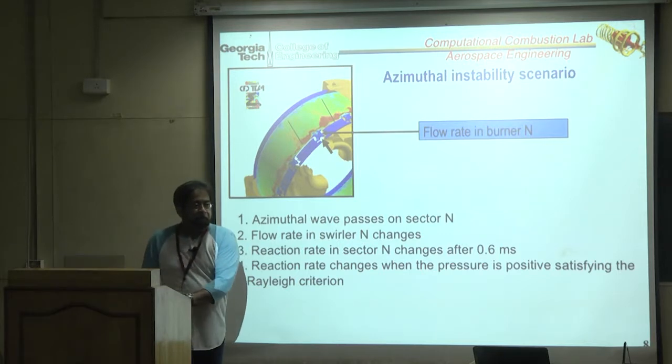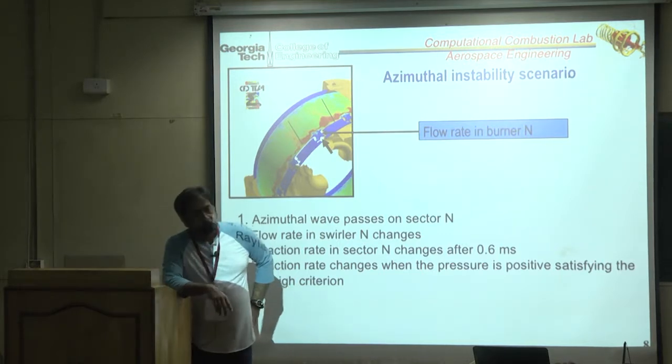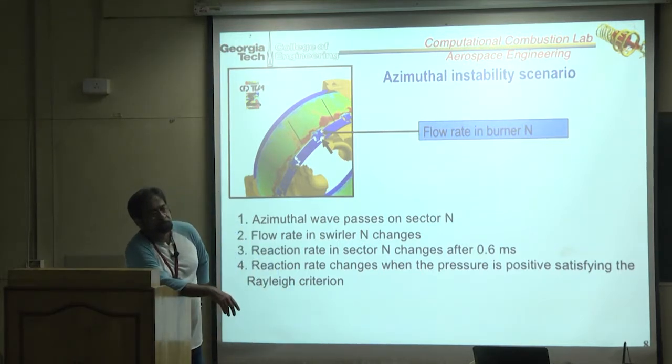Last session you mentioned that if you are going from fine grid to coarse grid, it's okay because we just eliminate some turbulent eddies. But if we have fine grid, then coarse grid, and after that fine grid again, there is a problem because we artificially generate turbulent eddies. Right, yeah.